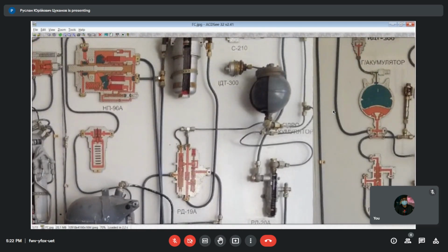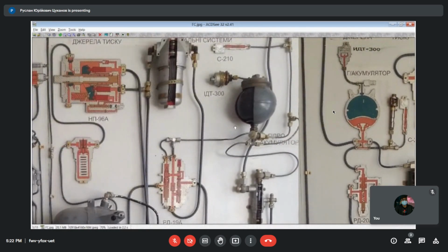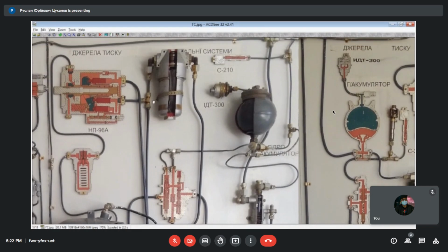So this is from the onboard pump, this is from the ground pump. According to the picture which you have in your lab work manual, in parallel to these engine-driven pumps, the power control hydraulic system has one more air turbine-driven pump, which is absent in this modification, and which is also attached in parallel, so to the T connection will be connected the outlet of the pump.